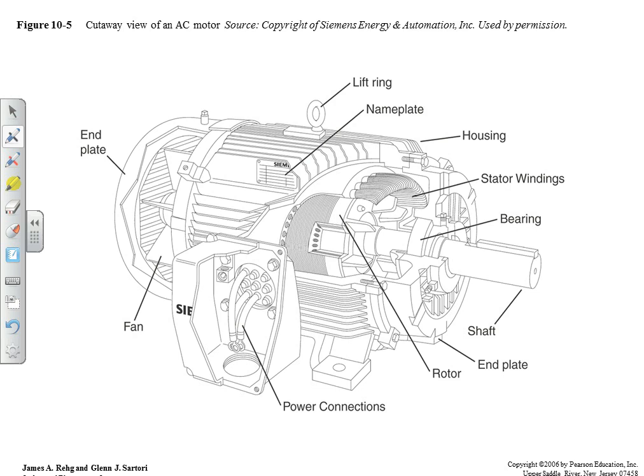But the smallest motor on a submarine is 10 horsepower. The biggest one is 200 horsepower. Well, you're going to need a lift ring. You're going to have some way to bring it in and out. In your usage, the stator windings and the windings of the rotor are things that you wouldn't deal with much. In a submarine usage, in a Navy usage, those things get replaced every 5 years. So every 5 years, all the motors get ripped out of a naval ship. All the windings are removed and they're rewound. And a tender would have a rewind shop that could rewind motors up to 200 horsepower in size.